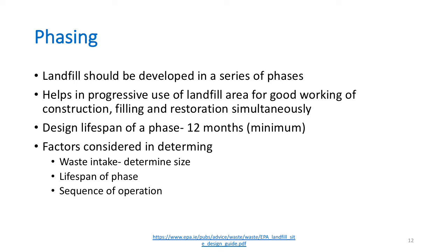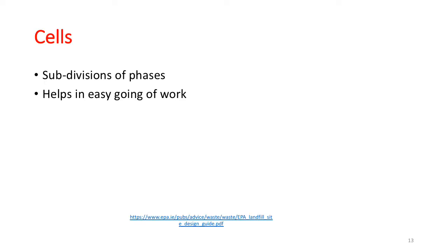Phasing. Landfill should be developed in a series of phases as it helps in progressive use of landfill area for good working of construction, filling, and restoration simultaneously. To avoid frequent and disruptive preparatory works, it is recommended that the design lifespan of a phase should be minimum 12 months. Factors considered in determining phasing are waste intake that determines the size, lifespan of a phase, and sequence of operation. Moving on to cells, these are subdivisions of phases and help in easy going of the work.